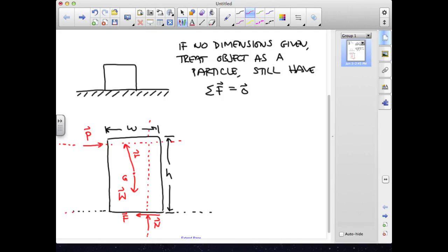The line of action of F is parallel to the floor, so again, it doesn't go through G and also has an eccentricity with respect to G. The sketch shows 4 forces acting on the furniture as you try to push it around your room. The forces P, F, and N are all eccentric in that their lines of action don't pass through the center of the furniture at G.